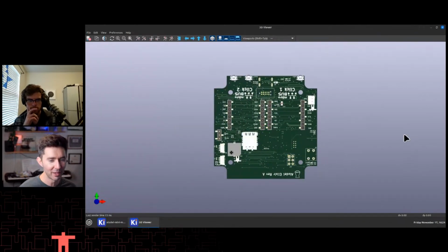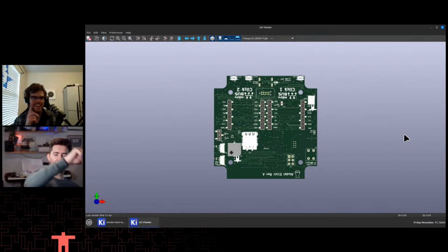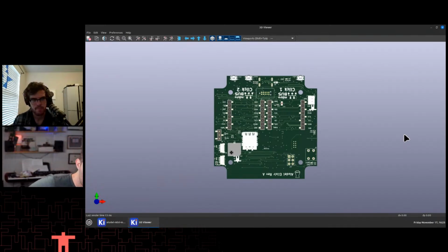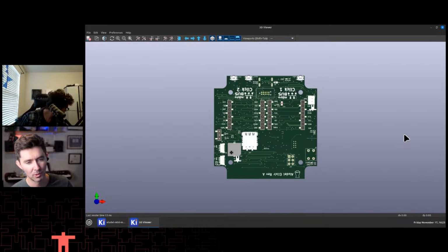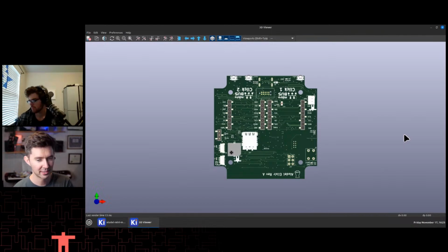But when you're making a board, you just put it all on there at the beginning, and then you try and exercise it using something like CircuitPython or a Zephyr shell to validate this stuff, right? So we were turning on LEDs using the Zephyr GPIO shell, and once you know that that's connected up properly, then you're able to evaluate other stuff that you put on the board.